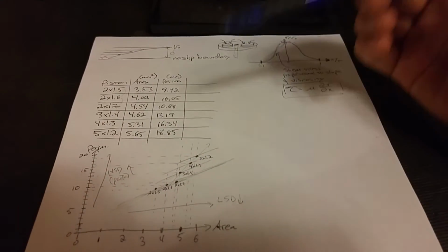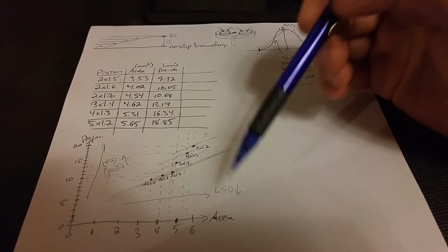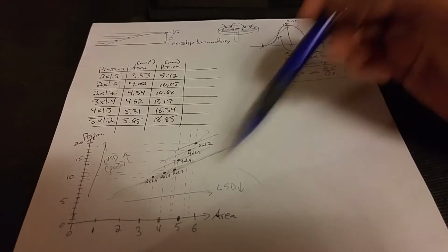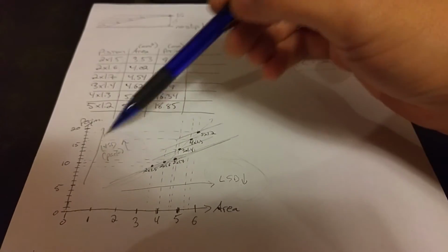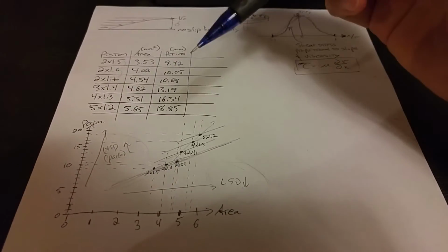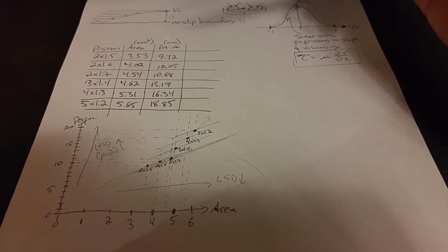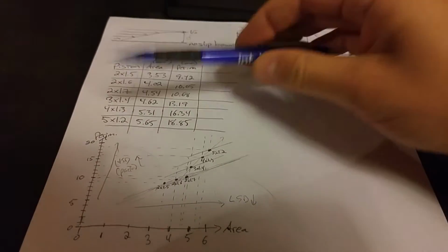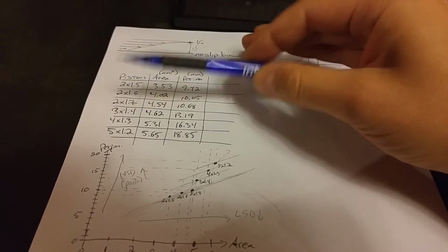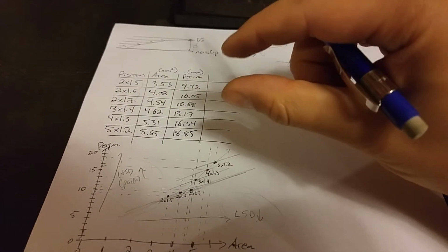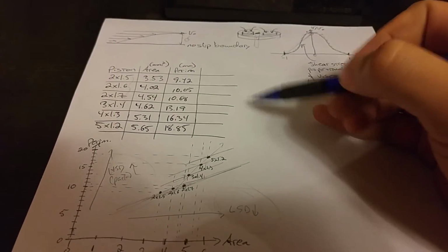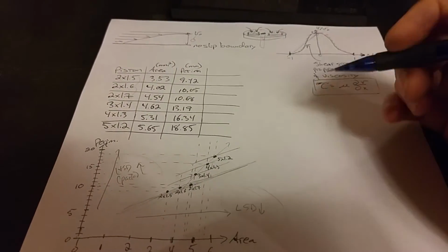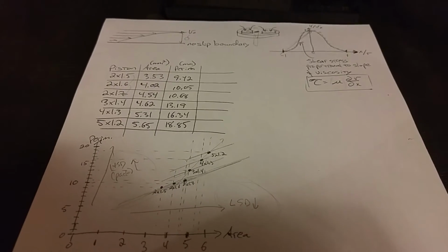If I'm negotiating a corner, that's just my low speed damping there. But the only thing that's impacting high speed damping on a smooth surface is when I'm landing off of a jump. Now if the surface is smooth and say relatively high traction, I might run the ride height rather low, or I might run a relatively low amount of droop on the suspension, which means my total suspension travel will not be as large as if I were running on, say, a bumpier surface.